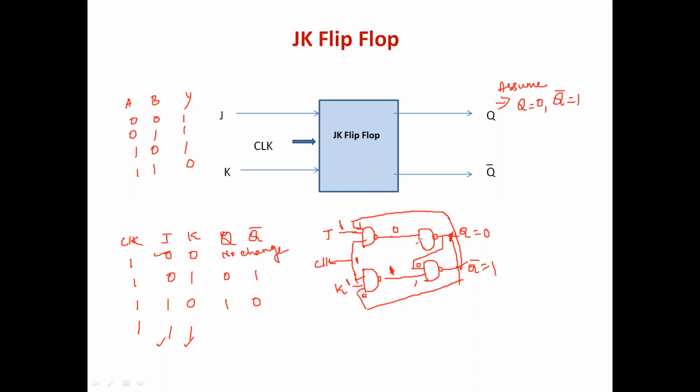So next, there is a connection here. When the input to this flip-flop is 0, irrespective of the other input, your output will be high. You make a note of this. High is very important. So this high is given as an input for this flip-flop. So 1 and 1, your output will be 0. Here you will get 1 because this 1 output is fed back to this NAND gate. So your output will be 0.